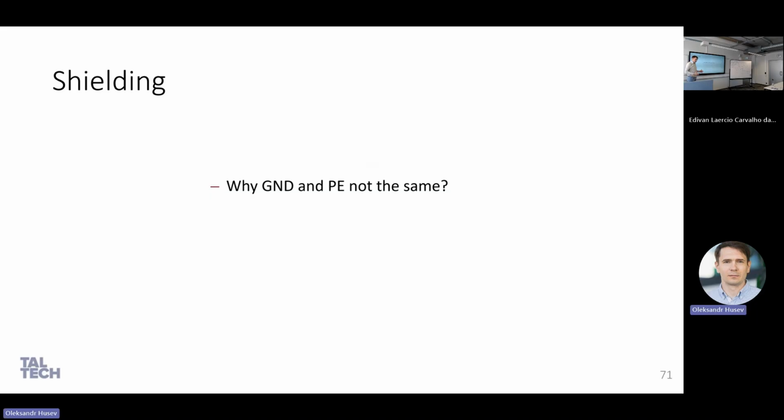Your static electricity, and so usually if you need to connect for safety reasons, no problem. If you have a ground plane which is used like a shield, it doesn't matter, connect it through a megaohm resistance or capacitors. But also pay attention, this is a Y capacitor, so the value should be in picofarads, not larger.